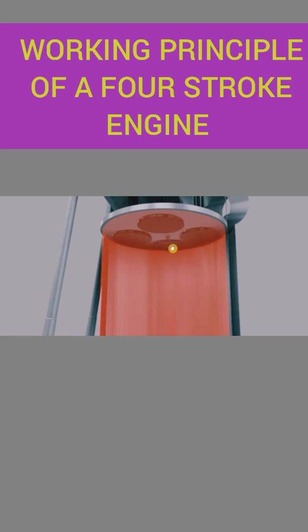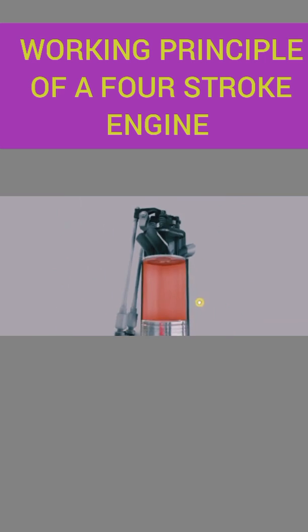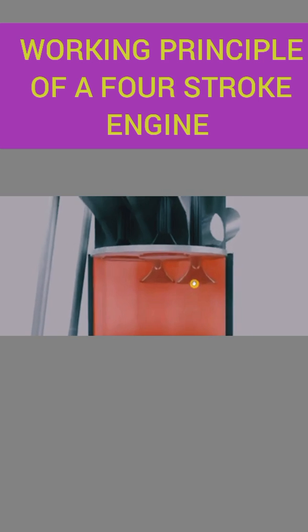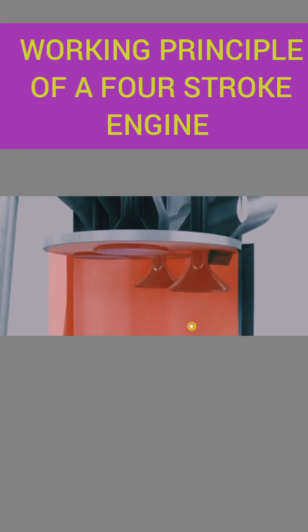As the exhaust valves open, it allows the exhaust gases that are inside the engine cylinder to be removed through the exhaust manifold. This removal process has a whole lot of function because it clears the engine cylinder of the exhaust gases and prepares it for the next combustion process to take place.